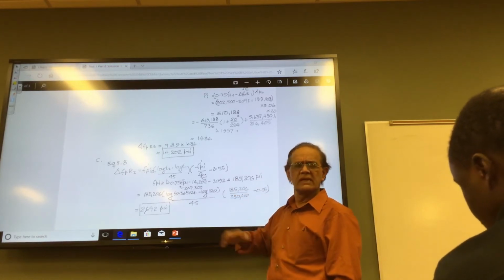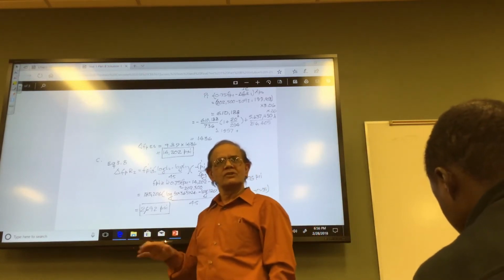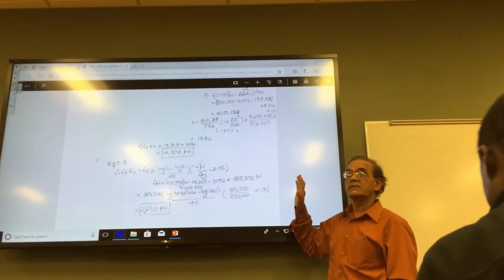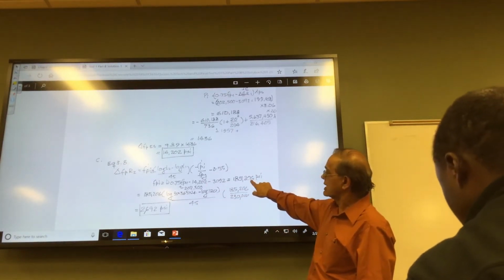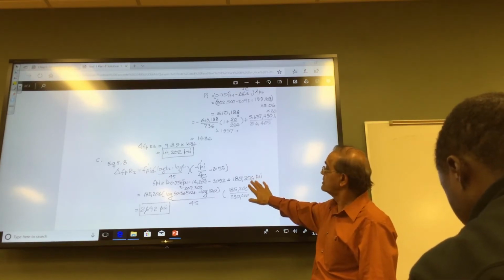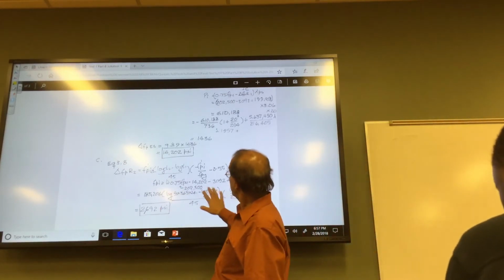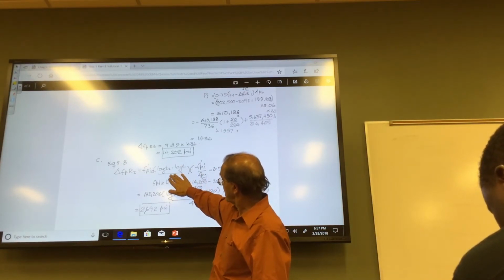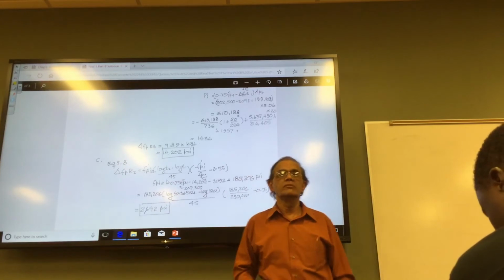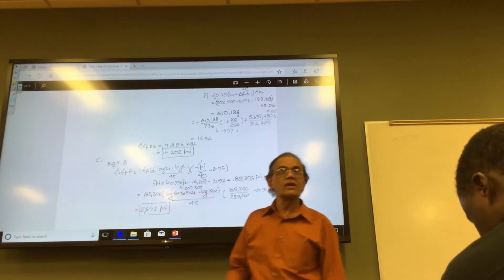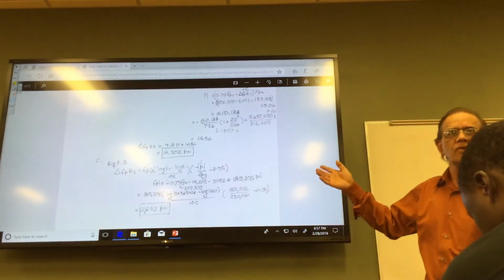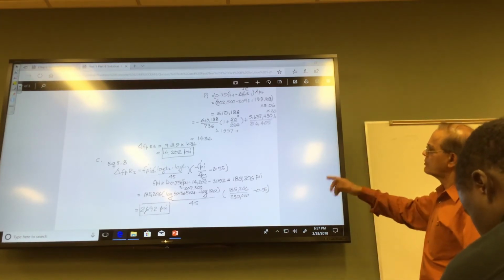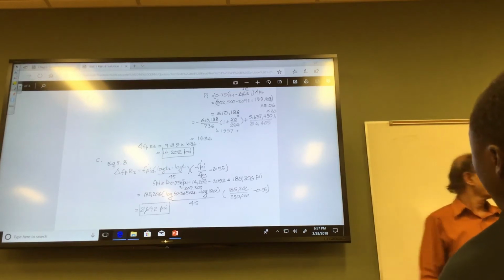right? So it's like you're depreciating your value, you're losing your pre-stress, so you keep account of that as you go, right? So at that stage, this is your PI at 5 days, and that's what you use. So once you include that, and the time factor, logarithmic, and whether you use 10 or 45 is equally good, you'll get this number. Now, if you use 10, then you'll get more like 10,000 PSI, which is okay. And if I have deducted your calculation by half or 1 point, let me know, okay?